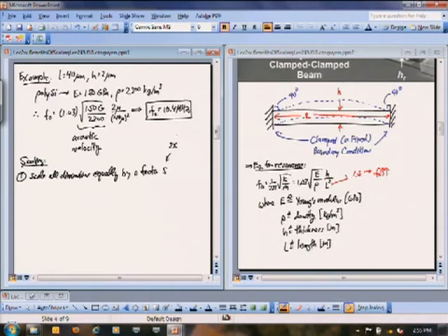And so how does that change the frequency? All you do is you take the frequency equation, which you see on this side right here, and you plug in S for any dimension that you're scaling. So I plug in an S for my H. So this is going to go as S in the numerator. I plug in S for my L, so S squared. So this ends up being 1 over S. Okay, so that means that if I scale this by 1/2 times, then the frequency will increase by 2 times, if I scale H with L.